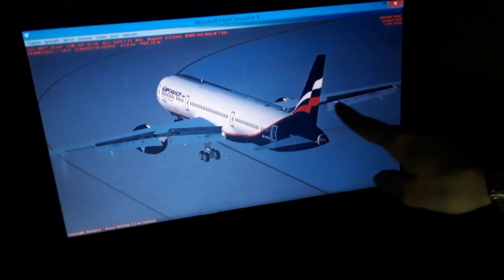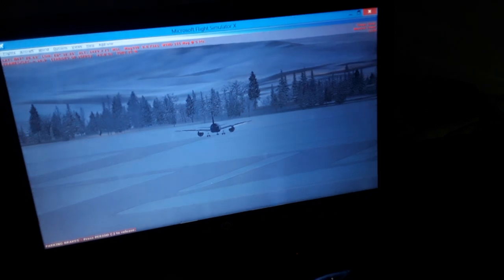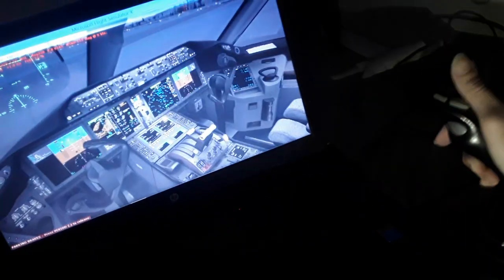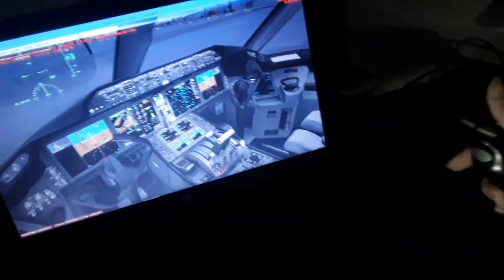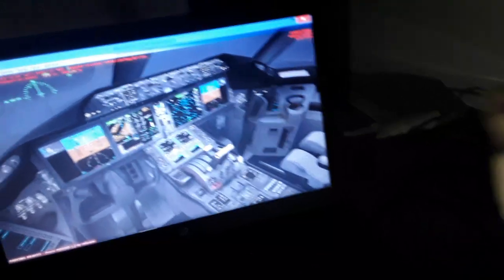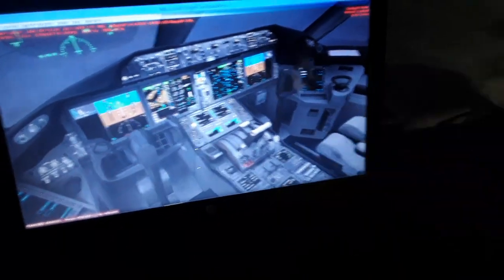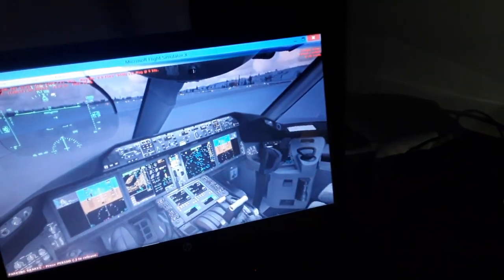You can see also all speed brakes are ailerons now, and also the flaps are extended. The speed brakes are the flight spoilers. So you can see left and right on the control wheel over here. Same thing as the side stick left and right, no difference at all. Also we have the stabilizer trim, which we need to apply together with the rudder pedals.